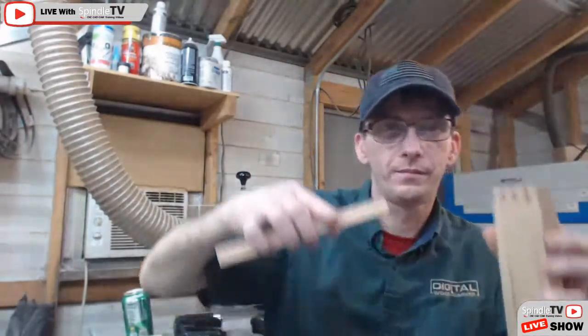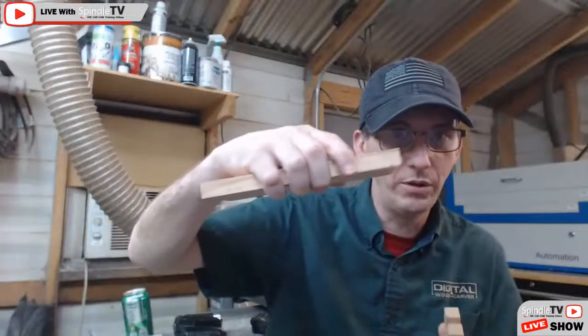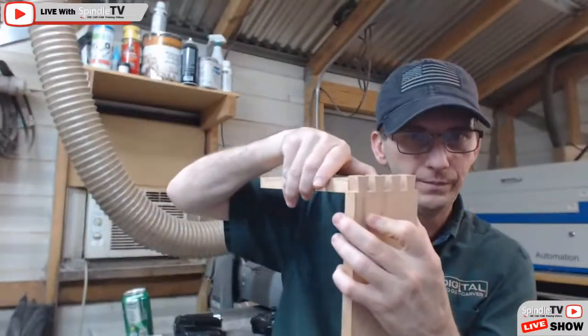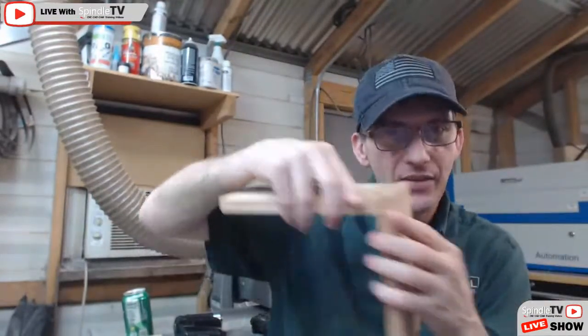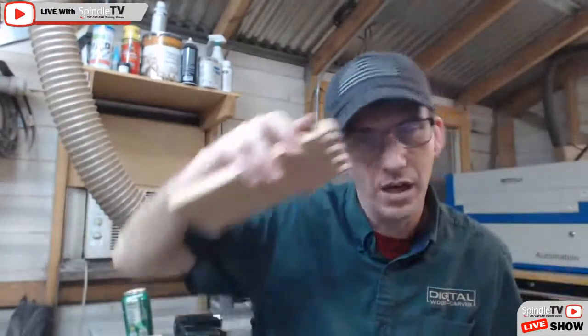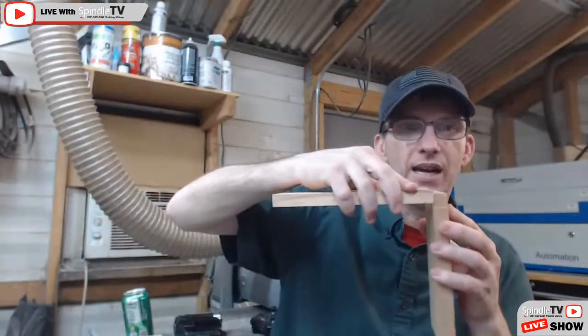Could you clamp a backer board to the machine bed and run the bit through the other way? Yes. I could do a horizontal board and a vertical board, whether it be a waste board or whatever. I can run the bit the other direction from the outside in, and that could be my backer board. Absolutely. I could clamp that as the backer board, and I could have a waste piece back there clamped down. You're absolutely right. I could totally do that.